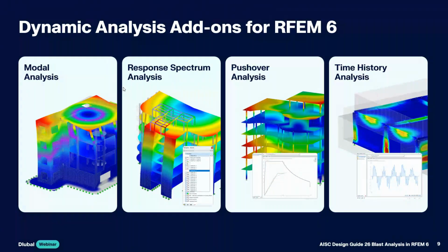So I'll give a quick overview, including this first add-on, the modal analysis. This calculates the structure's natural periods, the frequencies, and the mode shapes. We actually are going to carry out a quick modal analysis for our structure today for damping purposes. The response spectrum analysis will generate seismic loads according to standards like the ASCE 7 and the NBC. We have the pushover analysis add-on. This is an advanced seismic analysis taking into account the structure's nonlinearities. Now, we won't be touching on either of these more seismic-focused add-ons today.